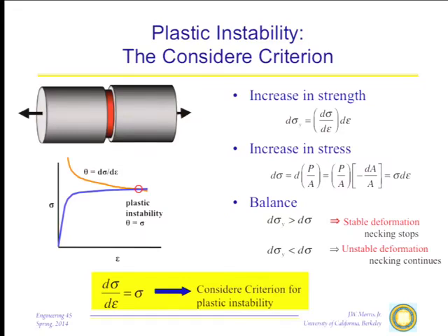Before we get to necking, what's happening is that every time there is an increment of plastic strain in the bar, that plastic strain hardens the bar, so that little local region stops deforming. The deformation goes somewhere else. And so it slowly but surely works its way up and down the bar. When we hit the instability, what happens is once that deformation happens, its increase in strength is not enough to overcome the increase in stress. So the deformation concentrates there. We get a necking, stress increases without bound until finally the material fractures. Now, what is the mathematical criterion that governs that?